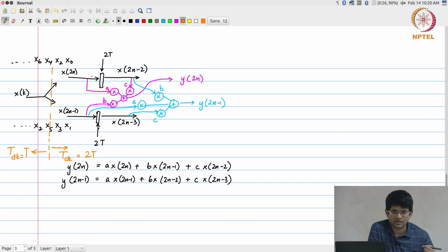Okay. Why is this important? Because if you actually try doing a timing analysis on the right hand side of this circuit that I have shown over here, what it means is that all your static timing analysis, your critical path computations and so on are now trying to meet a timing goal of 2t rather than t. It is much more relaxed, it is easier for it to meet that timing constraint. Okay. You can use, if necessary, you can even use slower multipliers and adders.